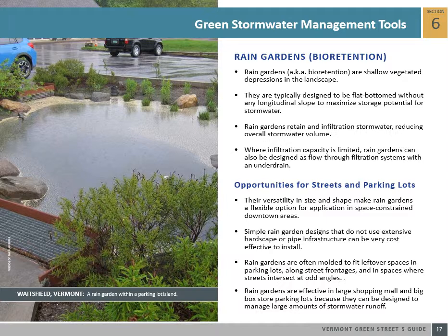Common constraints with rain gardens include required maintenance similar to perennial gardens, which may be outside the regular scope of municipal public works staff. Identifying a suitable maintenance plan and appropriate town staff to manage is critical for success. Rain gardens collecting large amounts of road runoff are prone to clogging without pretreatment. Space for settling particles, either in a catch basin sump or a forebay structure, is critical to avoid excess sediment buildup in the garden itself.